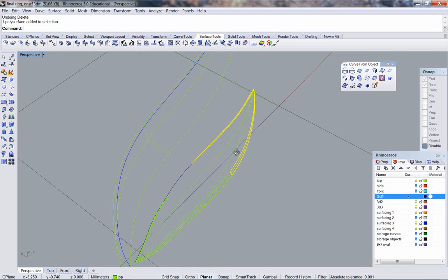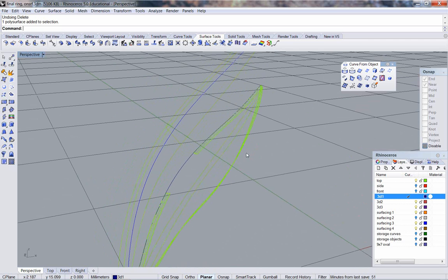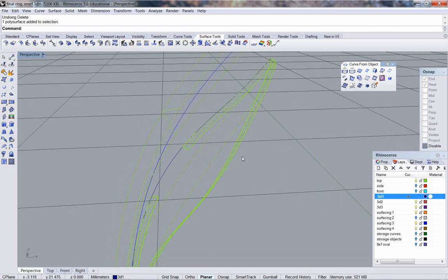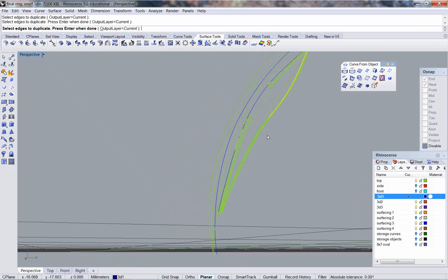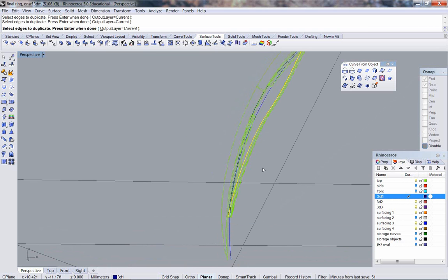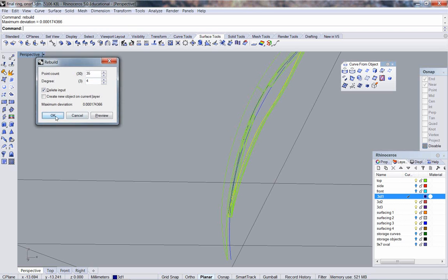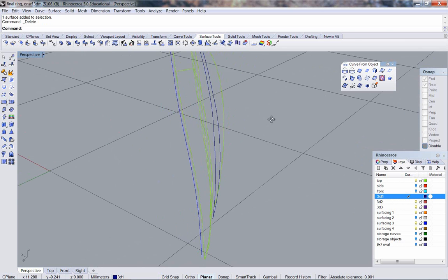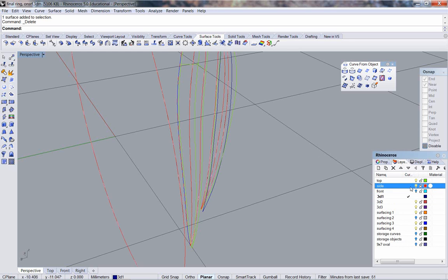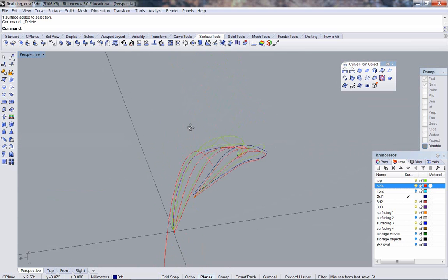Okay. Alright. Rhino 4 would never have done that. It's extruded this as one surface with a kinked end. Very inefficient choice for Rhino to make. And it does it more and more lately. Extrude those, extract those, join them, rebuild it. And now I can delete the extruded surfaces. See, there was a weird little scrap of surface there. Bring back my original curves.